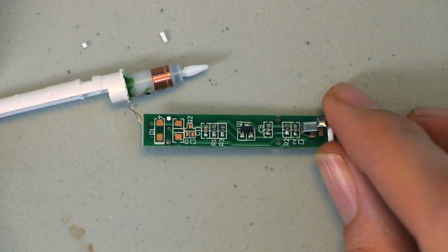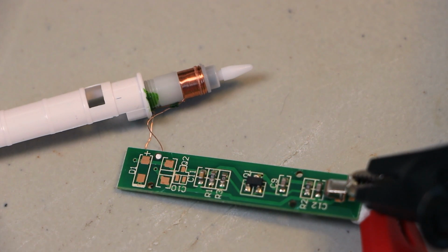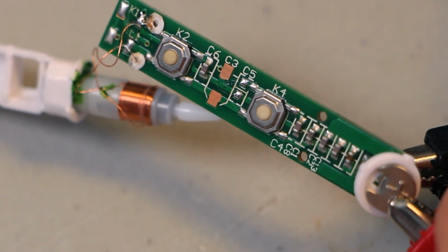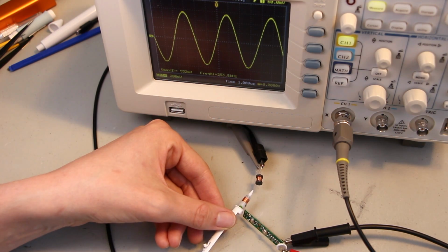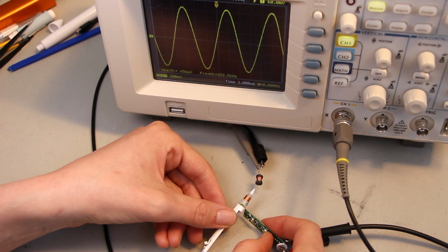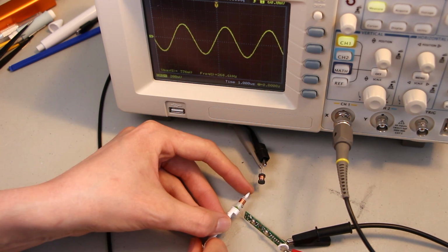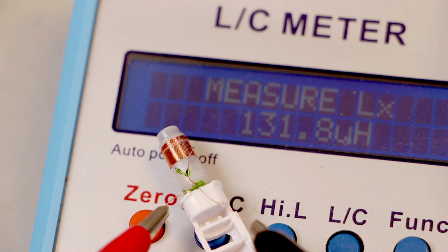The circuit inside the Huion pen is remarkably simple, and I think it's kind of elegant too. On this side you can see the 1 transistor, and on the other side we have the 2 buttons and a handful of capacitors. It forms a simple 1 transistor oscillator that derives its timing from the combination of a coil and a capacitance. These buttons lower the frequency of the oscillation by switching in additional capacitors. There's no sensor built into the tip, but we can certainly see the frequency increasing a little bit as we press it. Let's take a closer look at the transmitter coil.